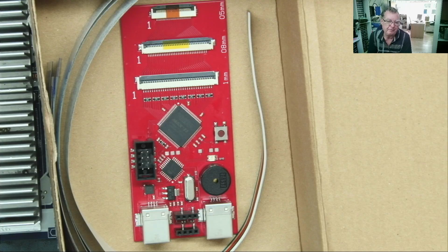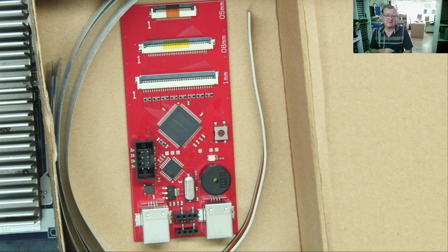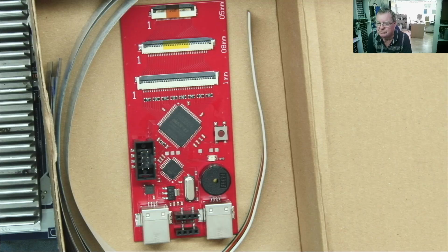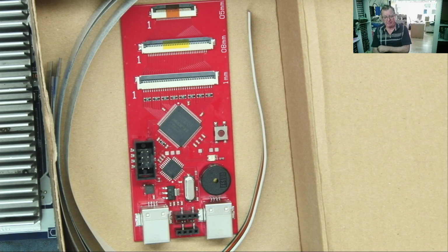Also, we have firmware in TVs on the T-Con timing control board. This will also program those. So, as I say, it's a specialist topic, but it's becoming more and more common these days. If you suspect corrupted firmware, then I suggest you get into the various repair communities, ask and see if anybody can help you. Maybe, once you're expert enough, you can help other people.